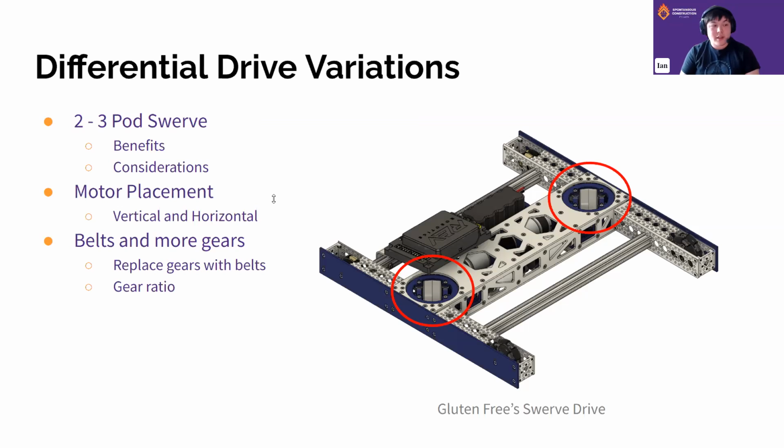So first off, if you have barely any experience in FTC, I'd recommend focusing on simpler drivetrains first, like Mecanum Drive, because this does require a lot of extensive experience in CAD to create all the custom parts that are necessary to make it. But if you do want to start looking into it, I'd recommend looking at both our Swerve Drive, KookieBot's Swerve Drive, they have a CAD posted of it, I'm not sure if they do, and Gluten-Free Swerve Drive to better understand how it works, and start from there with little steps by making a conceptual Swerve pod first, and then working up from there. Also, no matter what you do, always follow the engineering process. Prototype, test, find the issues, prototype again, which of course will take a lot of time.